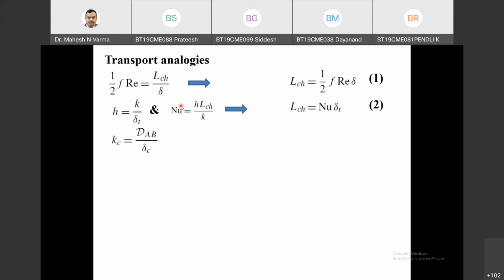As we were discussing the Nusselt number, what will be the equivalent dimensionless number in mass transfer? Roll number 8, Ali. Sir, Sherwood number, I think. Sherwood number, very good. What is the physical interpretation of the Sherwood number? Sir, convective mass flux divided by conduction. It is not convective divided by conduction.